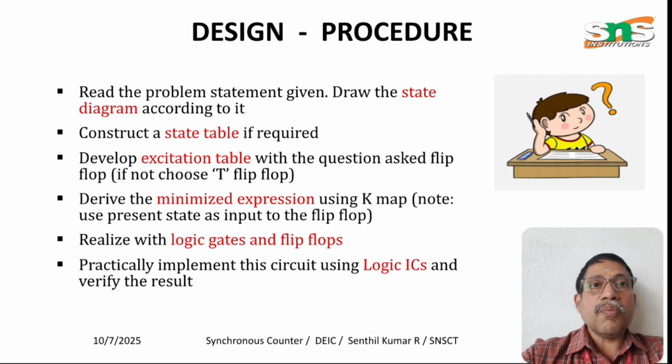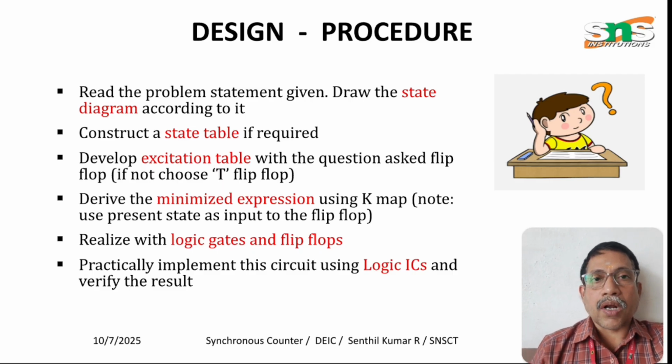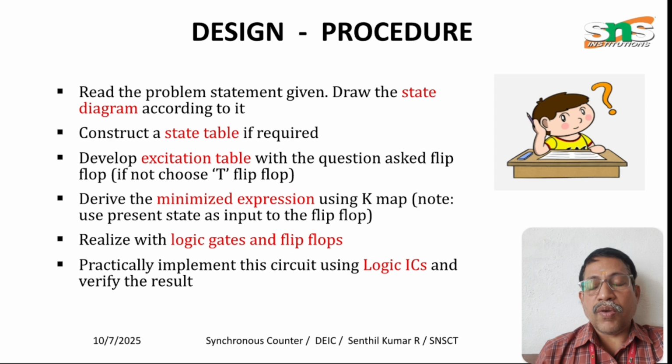Therefore, you have to read the problem statement first and draw the state diagram according to it. From the state diagram, the state table is constructed. If the flip-flop is given in the problem statement, then you have to choose that. Or we can choose the T flip-flop, the toggle flip-flop, since it is very easy to design.